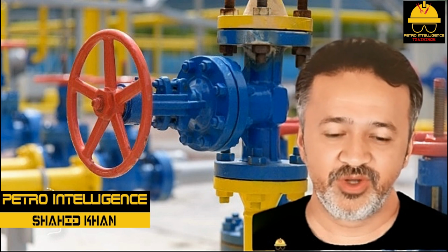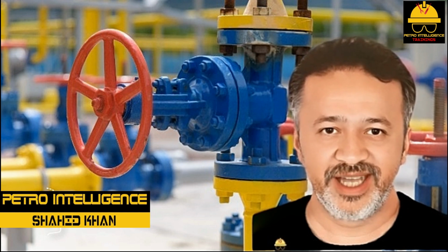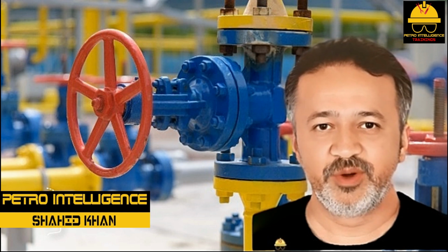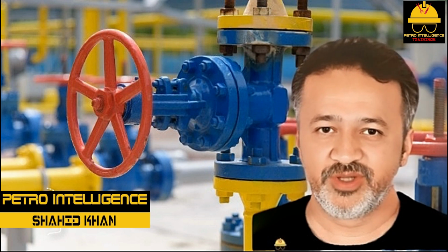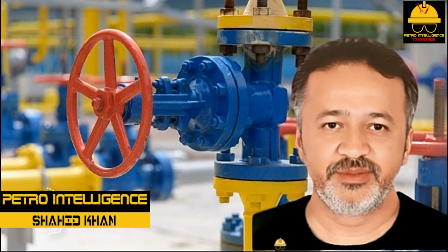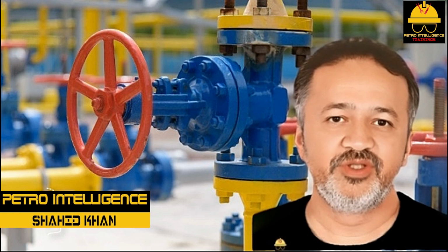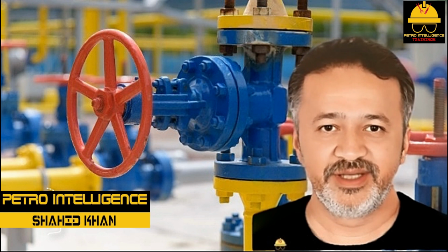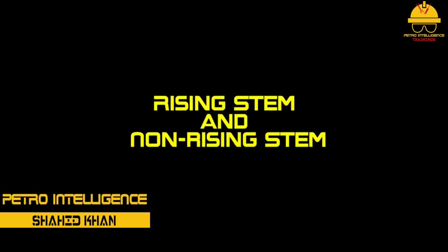Bronze gate valves are used in low temperature, low pressure service. Brass gate valves are used in low temperature, low pressure service. Cast iron gate valves are used in water, lubrication, and some low-pressure steam services. Gate valves are considered excellent devices for process services that are used intermittently. It is not uncommon to find gate valves that have not been operated for many years.